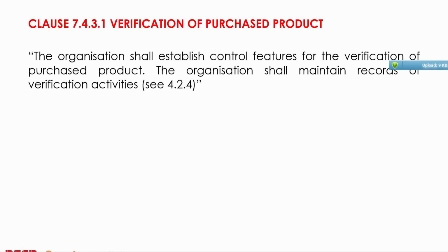Verification of purchased product. Verification is often done by the goods in department, by the parent company, inspecting the raw materials. This is expensive, and these days sending material back has knock-on delays, which extend the delivery times and destroy reputations. The policy should always be to inspect at source, with the function of the parent organisation being quality assurance rather than a quality control one.